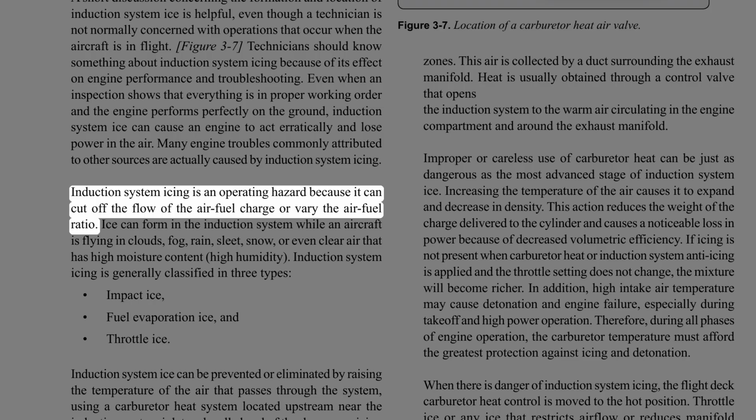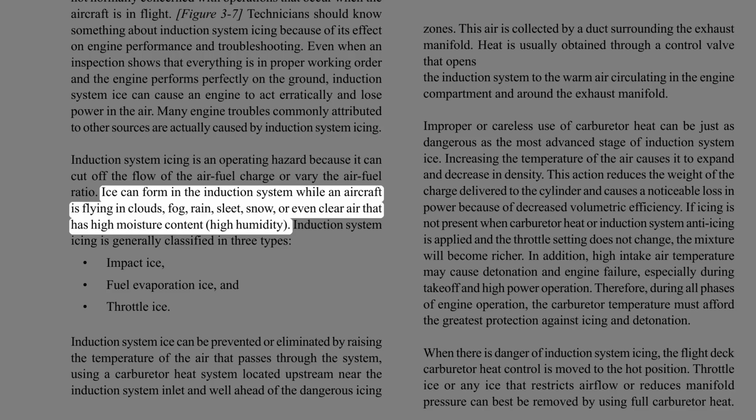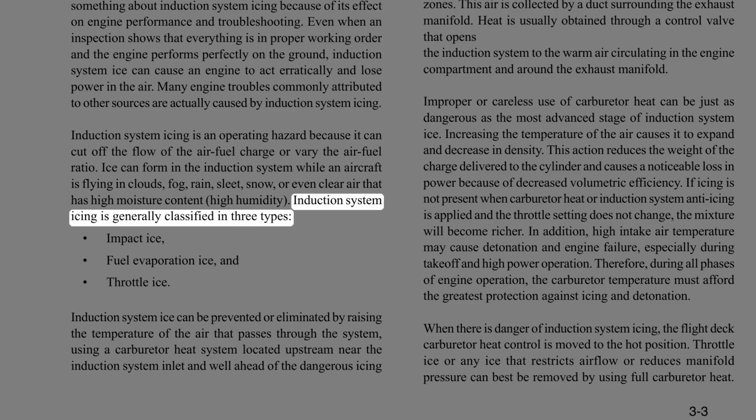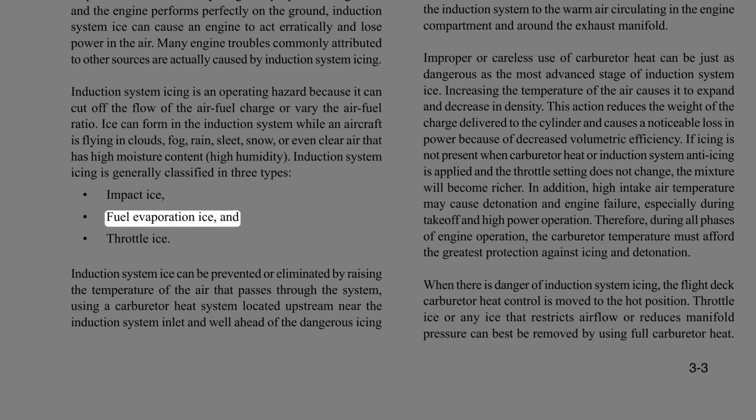Induction system icing is an operating hazard because it can cut off the flow of the air-fuel charge or vary the air-fuel ratio. Ice can form in the induction system while an aircraft is flying in clouds, fog, rain, sleet, snow, or even clear air that has high moisture content, high humidity. Induction system icing is generally classified in 3 types: impact ice, fuel evaporation ice, and throttle ice.